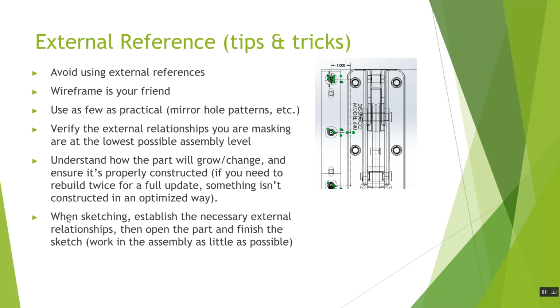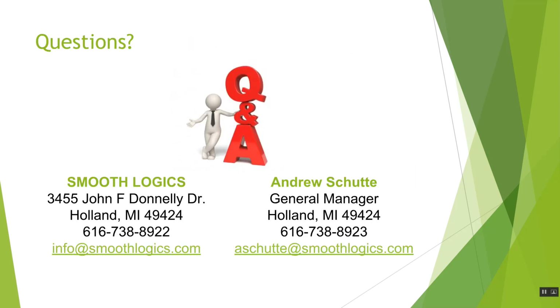Understand how your part's going to change. And when sketching, establish the necessary external references and then finish it as little as possible. Working inside the assembly as little as possible.